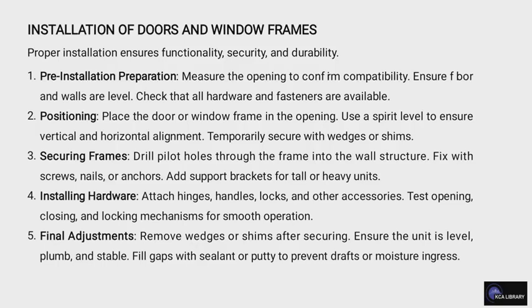The next is installing hardware, where you attach hinges, handles, locks, and other accessories. And the last one is final adjustment, where you remove wedges or shims after securing, ensuring the unit is level, plumb, and also stable.